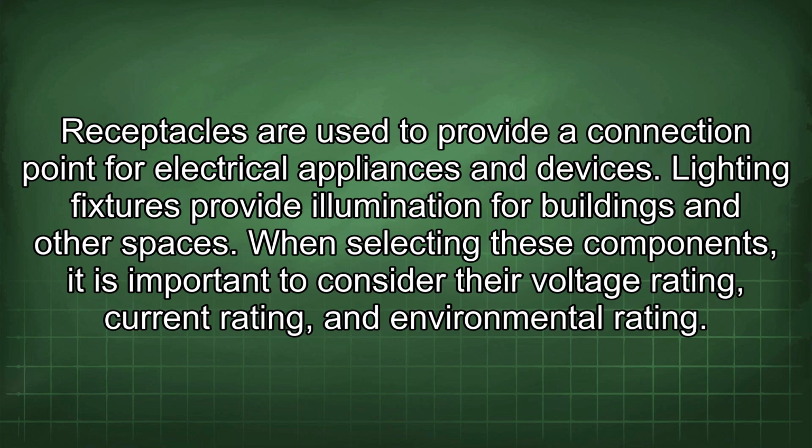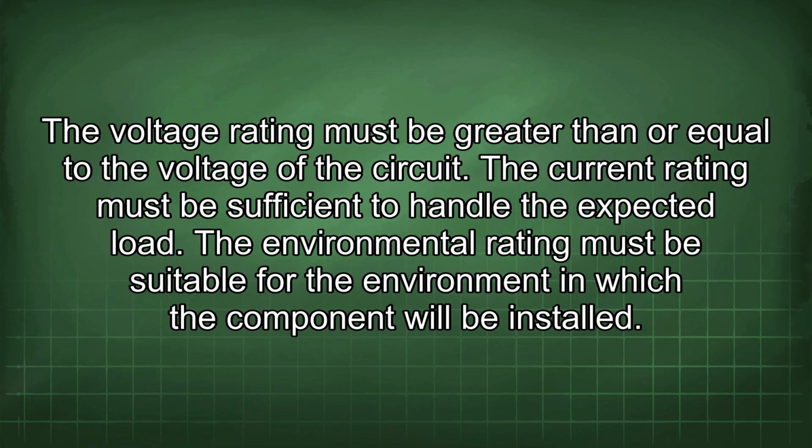When selecting these components, it is important to consider their voltage rating, current rating, and environmental rating. The voltage rating must be greater than or equal to the voltage of the circuit. The current rating must be sufficient to handle the expected load. The environmental rating must be suitable for the environment in which a component will be installed.